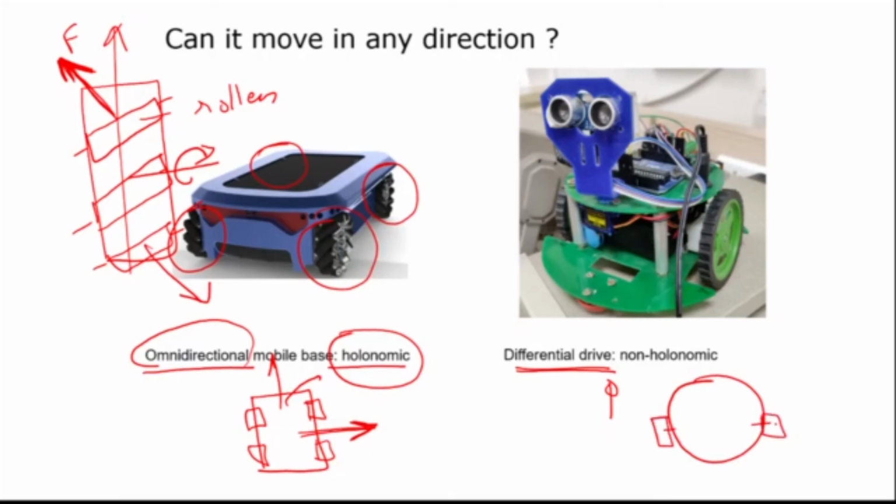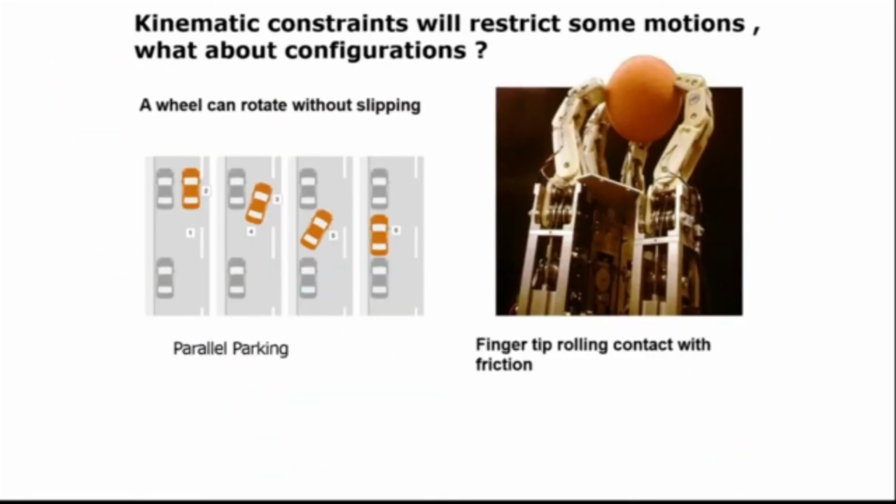So this is a non-holonomic mobile robot in which we have two side wheels and a caster wheel in front. Okay, now in this, depending on the direction of rotation of the wheels, this robot can go forward, it can go backward, and it can turn about its axis also, but it cannot go sideways. Okay, sideways motion is not possible. Now such a robot is a non-holonomic robot. Okay, now there are many examples of such systems in the real world.